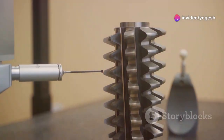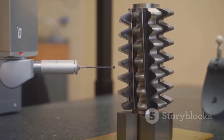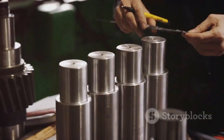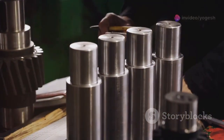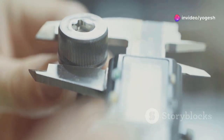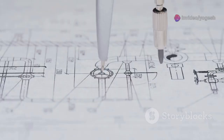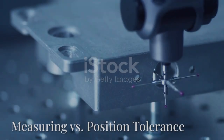The full frame might read concentricity symbol, 0.05, datum A. This means the feature's axis must be concentric to datum A within a 0.05 mm cylinder. It's a precise, universal instruction for machinists and inspectors. That's how concentricity is communicated in engineering drawings.